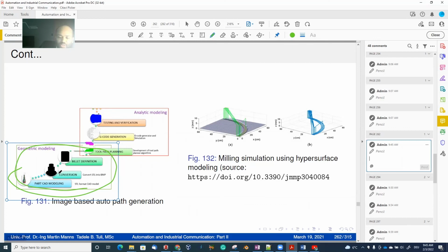So in such a situation, what I did was, initially, I had to import the model into MATLAB in STL, and in point cloud as well, and then I had to convert it into a bitmap image in order to simplify, because point clouds are too heavy for MATLAB.